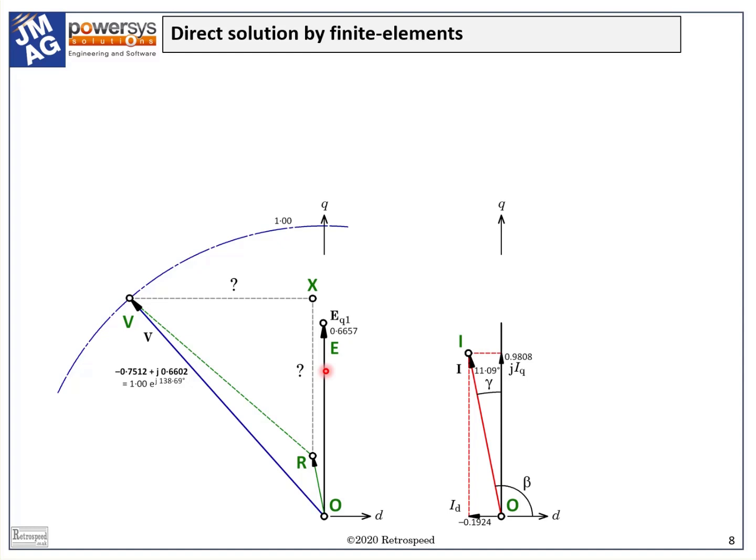We can see from this why it is not unreasonable to try to abandon inductance and reactance altogether and simply work with flux linkage, which is, I would say, the natural variable of a field solution, unlike inductance, which is a derived variable.